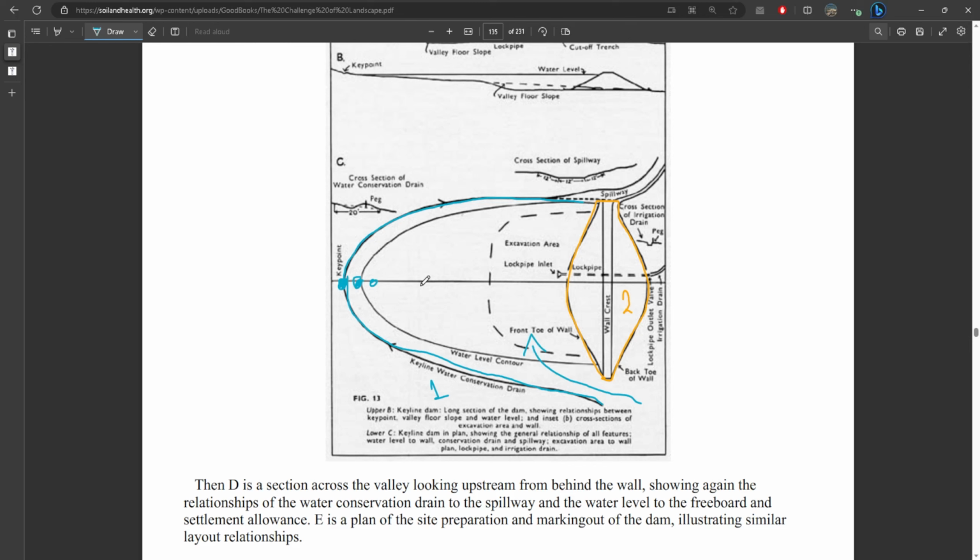So that way reduces the amount of maintenance you have to perform on this dam to keep it in good condition. Whereas if you build a channel right here at the side, it will start creating erosion most probably, and it's not a very convenient spot for creating settling pools. So it will probably increase the amount of maintenance that you have to do to this dam.